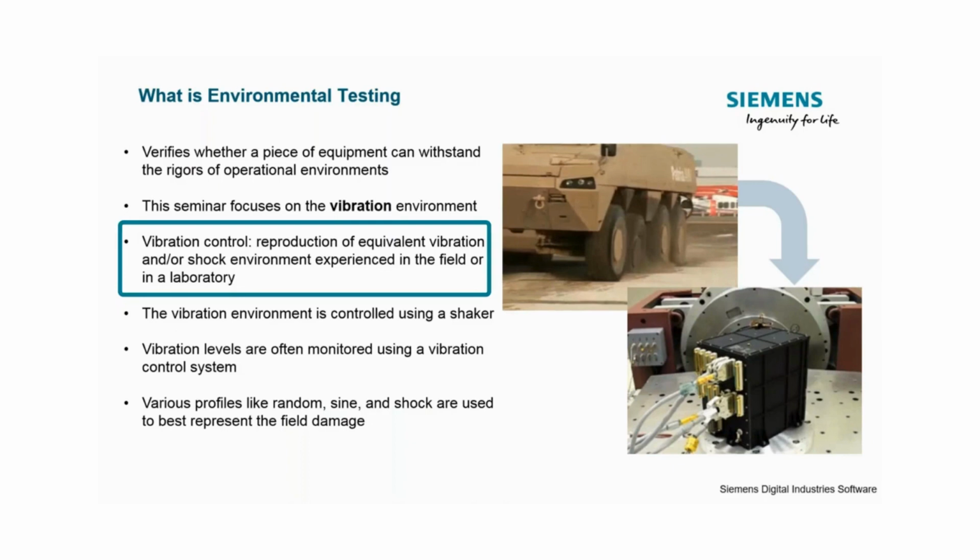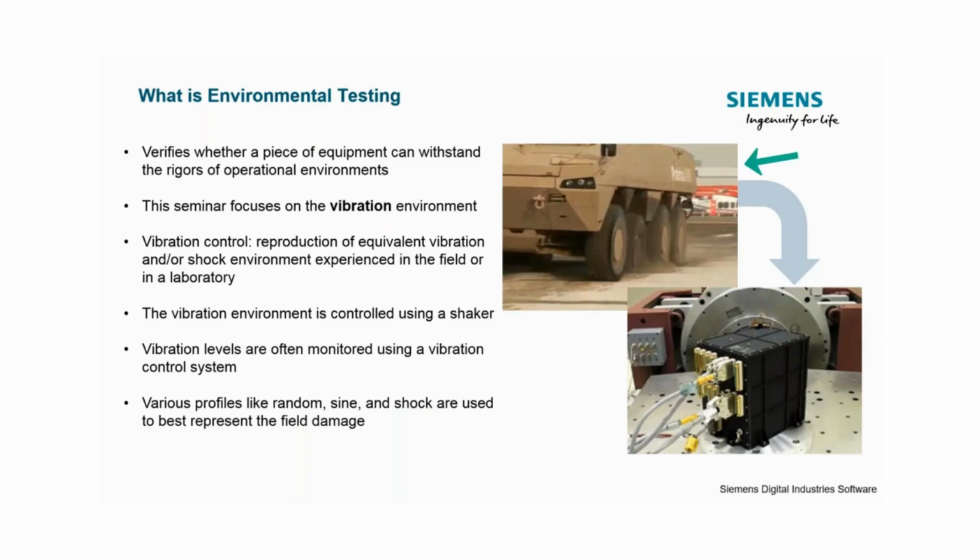So vibration testing allows engineers to validate the reliability of their products through controlled testing. And these vibration tests are going to accelerate the durability validation process by producing an equivalent lifetime of contributions of vibration, but in less time. So in this picture, what we have is, on the left, a field vibration where we're gathering some data on this profile, and then we're going to reproduce that vibration on a shaker table.